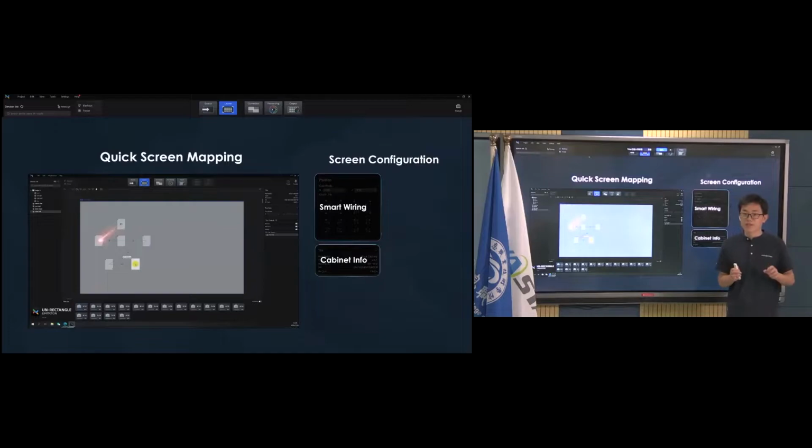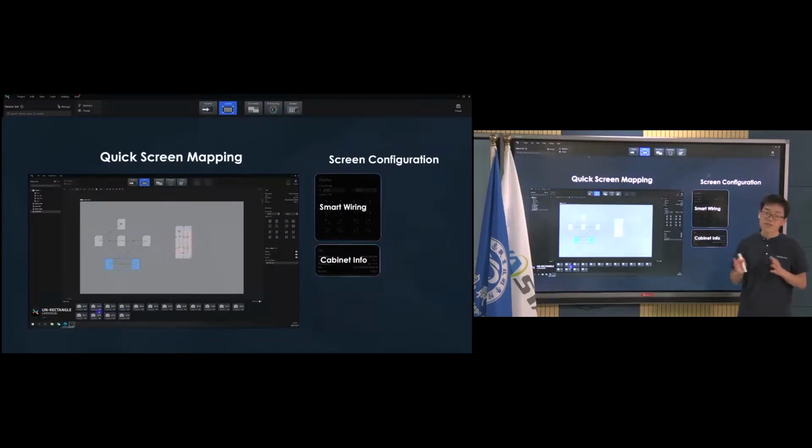Also, as I mentioned in the story, for the irregular screen, in the past, we had to do the calculation. We had to make sure the outer rectangle of the irregular screen was under the loading capacity of your controller. But now, with the new software, you can go the way you want, because we broke down the outer rectangle limitation. All the loading capacity and controller count will be based on the real cabinets you load.